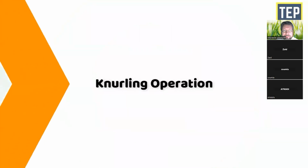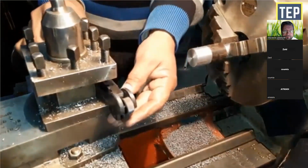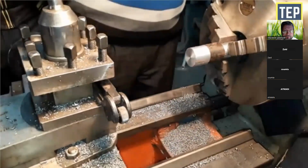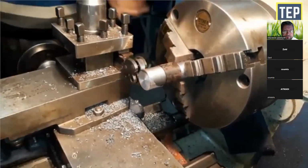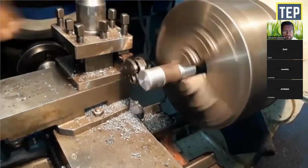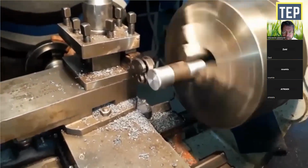Knurling operation. It is an operation of obtaining a diamond shape on the workpiece for gripping purposes. This is done to provide a better gripping surface when operated by hand. It is done using a knurling tool. The tool consists of a set of hardened steel rollers, and it is held rigidly on the tool post. Knurling is done at the lowest speed available on a lathe. It is done on handles and also on the ends of gauges.